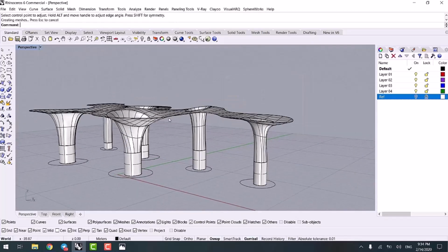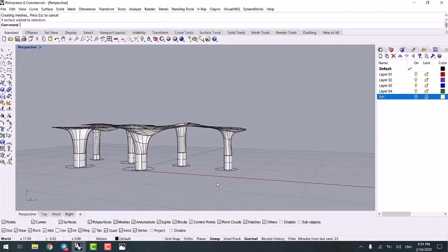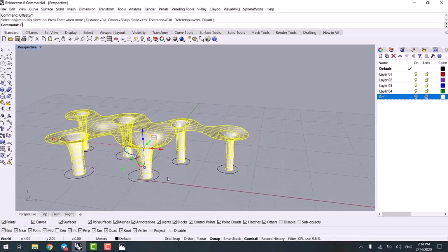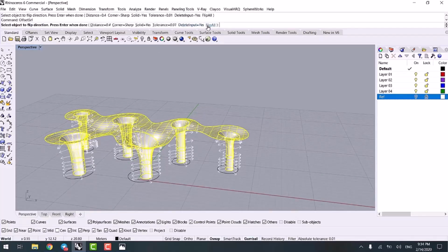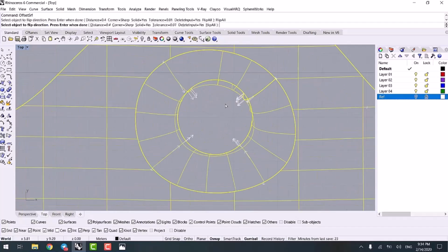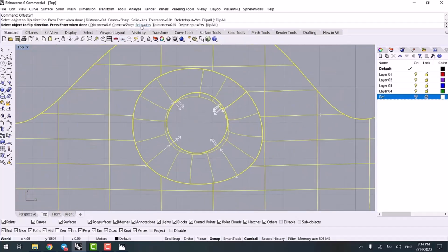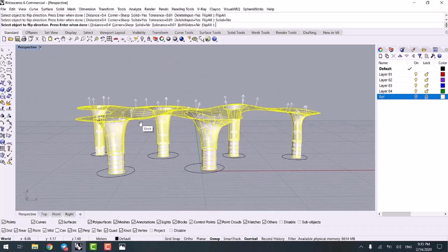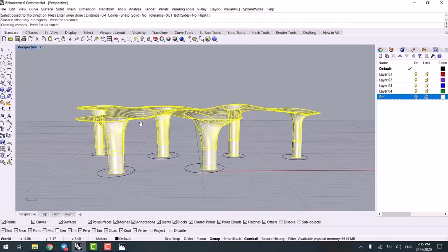Now, after that, with the cell surface command, select all the surfaces or plates, Control J, and with the help of offset surface, create a surface. For example, 4/10ths and solid no, create a surface to the inside. Okay, just like this.